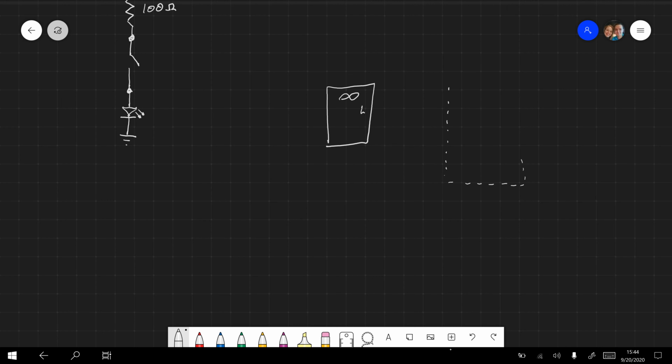And you could make a little box, and then you could say pin 4, maybe label it D4 for digital pin 4, and then you attach it to something, and make sure you've got your nodes in there. We're going to just say that this is a 100 ohm resistor, and then I've got it going into a diode. And then that diode goes into ground. So maybe make this box a little bit bigger. Make this an LED. And then send it to my ground pin.